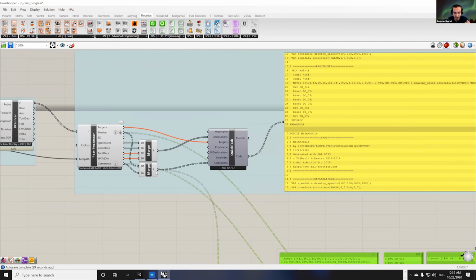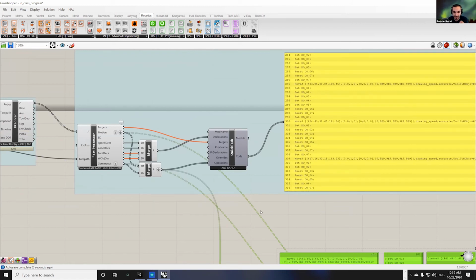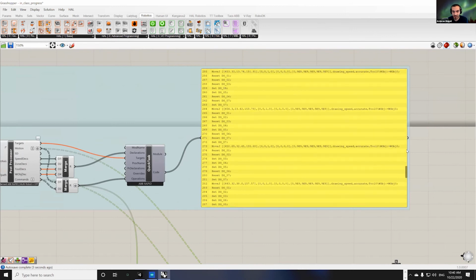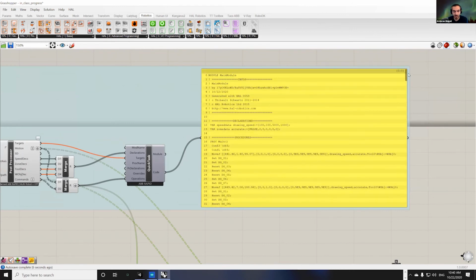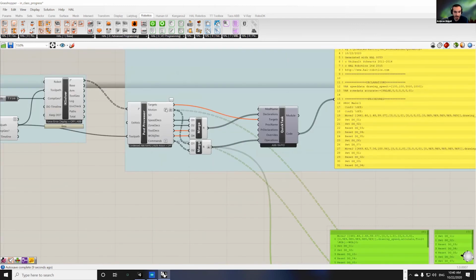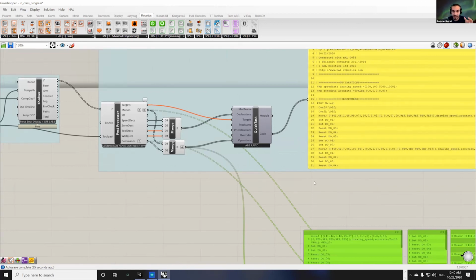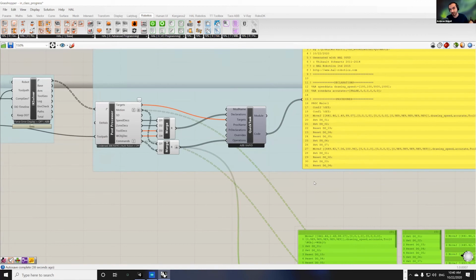The solution for this is to flatten our data and kill the data structure, so RAPID is going to put everything in one procedure. So we did a simplification on our motion and on commands to simplify the data structure. We applied graph to break down our motion commands into 40 branches of data so it could match our commands from here. Then we merged them together, so they actually connected to each other in the correct order. And then we flattened them in order to have them in one piece. So this is a really complex procedure.